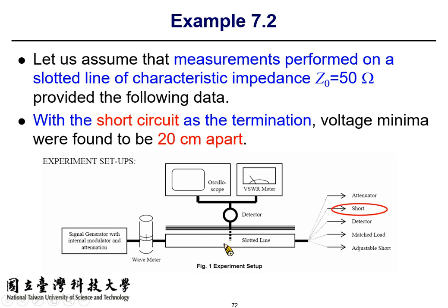However, if you put a high impedance voltage probe, a high impedance electrical field probe, inside the waveguide, you can measure the voltage with a certain conversion equation. You can get the electrical field intensity within the waveguide. At the right end of the transmission line of the waveguide, you can exchange for different types of termination.